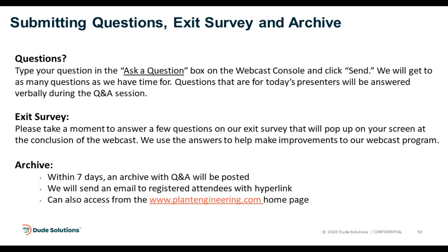No, by no means. You've got challenges on the physical world to have the expertise to retrofit those assets. But making the connection to your CMMS, like Asset Essentials, that's becoming easier and easier, because if we can be delivered that data electronically, it's pretty easy data. It's an asset ID, what is the reading, pressure, temperature, run hours, cycle count, a date and a time and a value. You get that into your CMMS, and then good things can happen from that, primarily in terms of generating a preventive or a corrective maintenance work order.